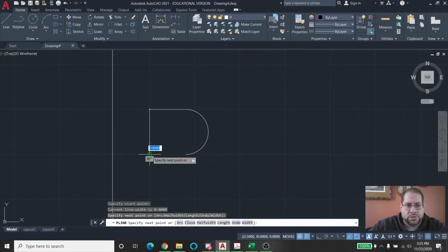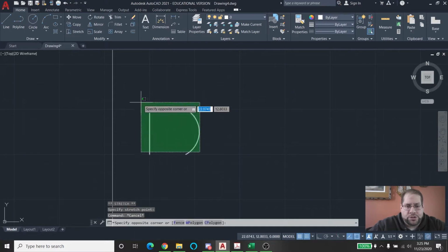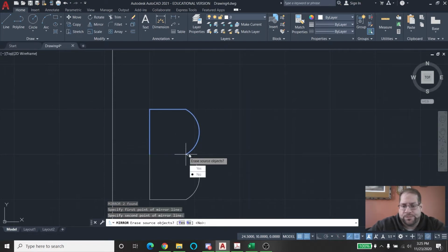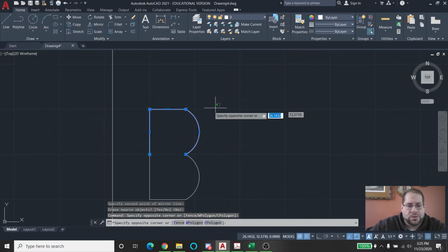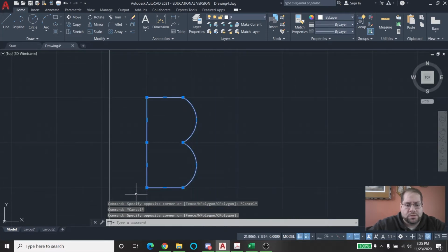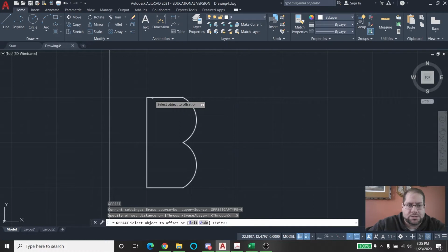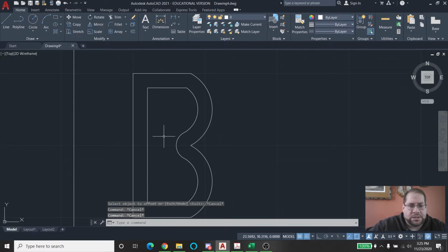Gonna do this in a couple of parts. I like polylines. They really provide a good amount of flexibility to work with. It should be okay. Now I'm gonna mirror this over here. That's good. I will join everything here. And now I'm going to offset some of those polylines by half space. See how that looks after I clean it up.